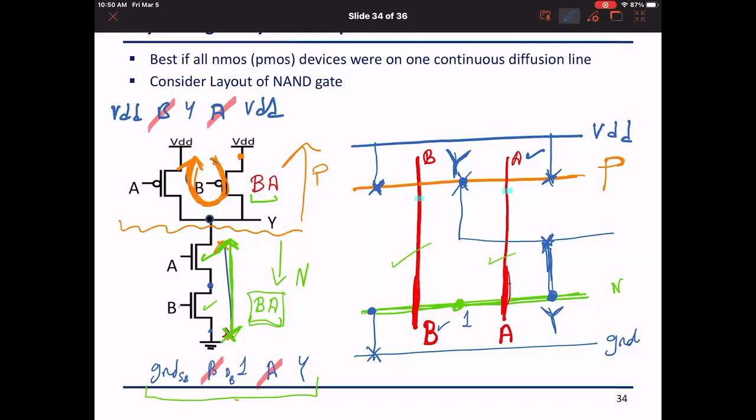And then it went over transistor A, of course this is the common node, and then it visited the drain node of A. If I want to explain this in another way, it visited source B, then the transistor itself, then the drain for B, then the source for A, then A, and then the drain for A. But we prefer to name them by their real names. So it crossed first the ground, then the transistor, then common node 1, which is common to A and B, then transistor A, then node Y. So this was ground, B, 1, transistor A, and then node Y, pardon me.